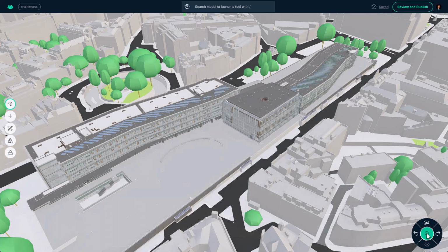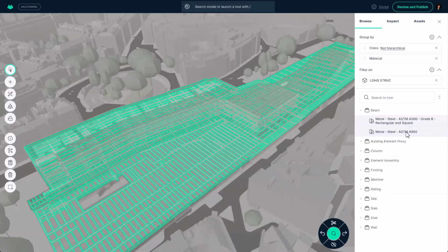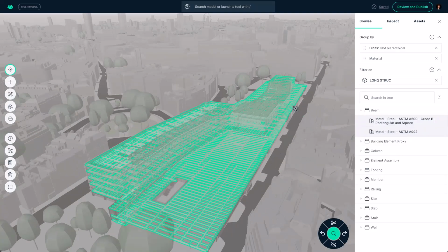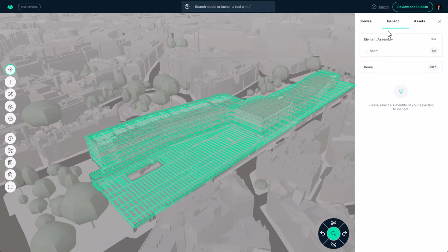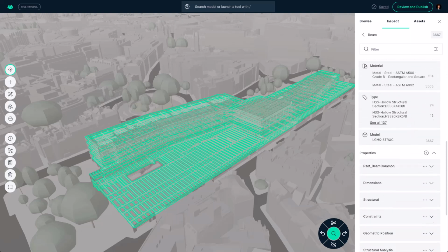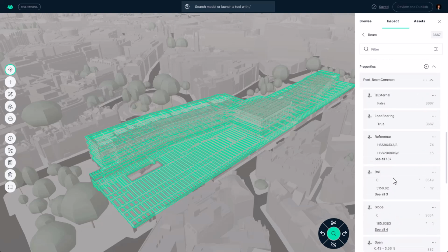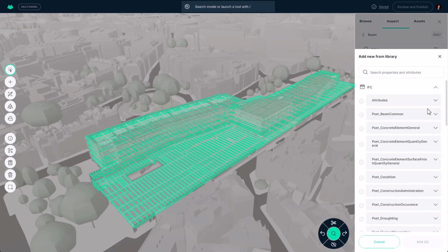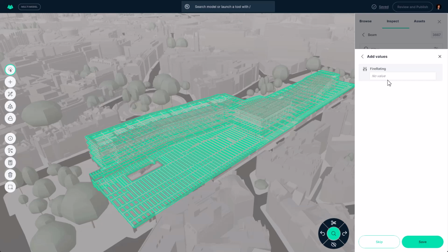Also, next to geometry, it is possible to work with the data in Qonic. It is possible to edit IFC properties, materials, spatial locations, and also classification systems and measure codes. In Qonic, you can use libraries, which allow you to use and work with data and properties consistently across different models in a project, but also even across different projects. In this way, you can make sure that the BIM data is always structured, consistent, and correct.